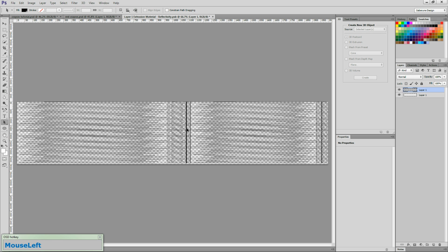In this case, pure white or full transparency is going to have no effect on the texture. In other words, where there's transparency, the numbers in the field of the properties pane will determine the effect. On the other end of that, pure black will completely nullify whatever numbers are in the field, forcing them to return a value of 0 for the areas that are covered in black. Using shades of gray will allow a partial effect depending on how dark that shade is. For this particular application, I think it's safe to say that the label will have virtually no reflectivity, so what we need to do is cover the label area of the diffuse with a pure black square.